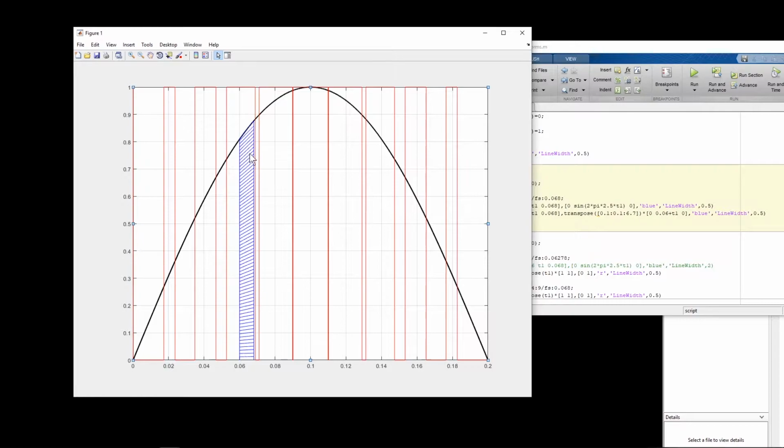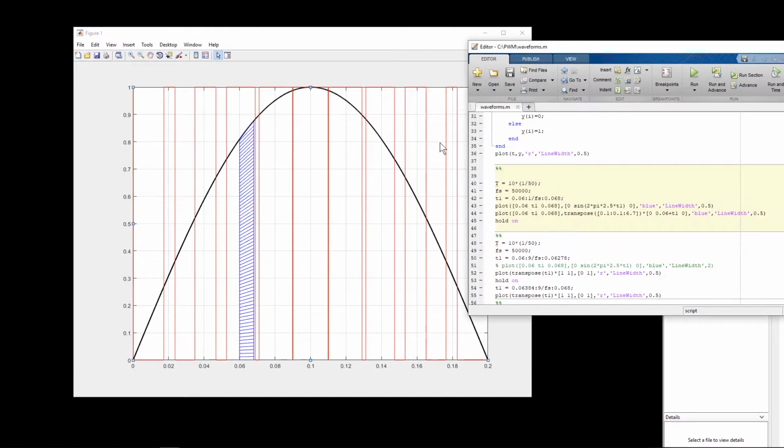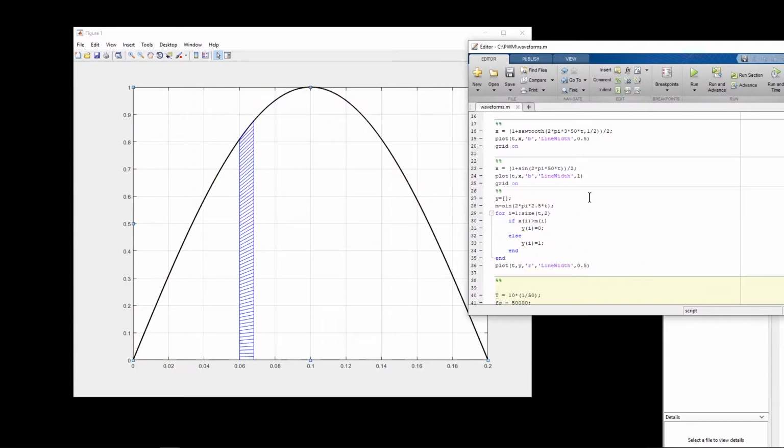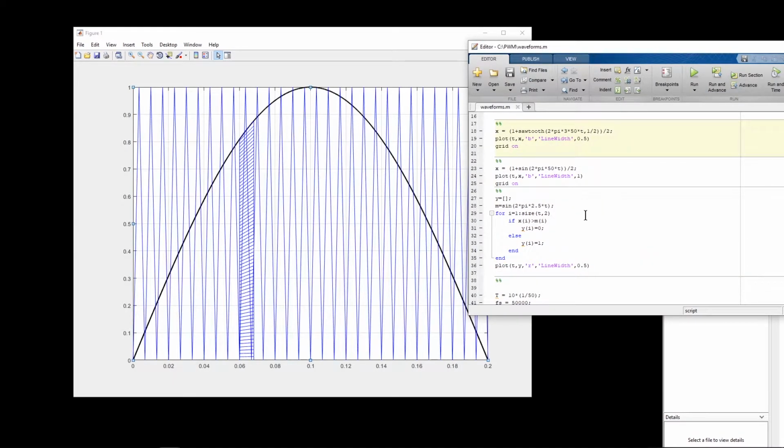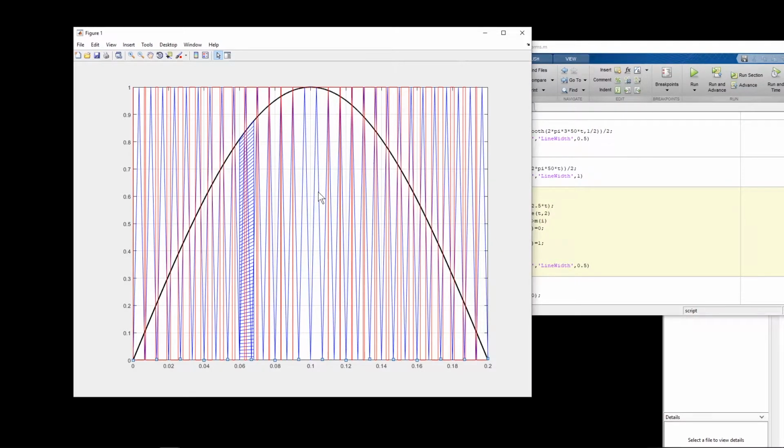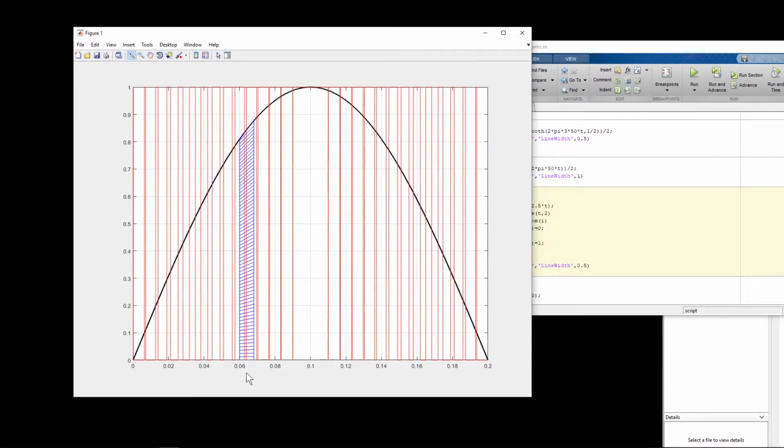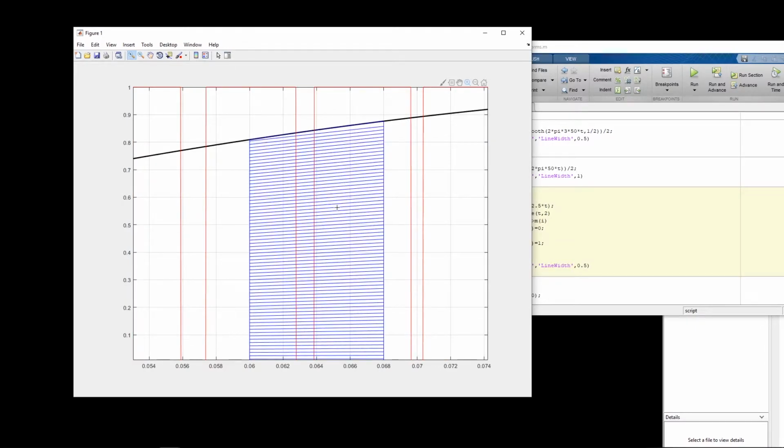Now obviously in this case they are not equal, even though we use triangular waveform as the carrier signal, but the reason is because the frequency of the carrier signal is not very high. So if I increase the frequency of the carrier signal, you notice that here I have a higher frequency, and if I plot the PWM, we notice that, for example, this integral, the blue region, would be more or less similar to the integral of the PWM signal, because PWM has some extra region on this section and also on this section, but instead it doesn't have the middle part. And actually, if we increase the frequency of the PWM even more, then these two integrals, the blue and the integral of the PWM, will be exactly the same.